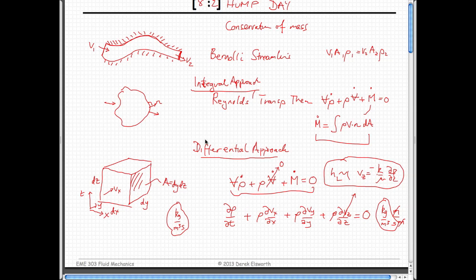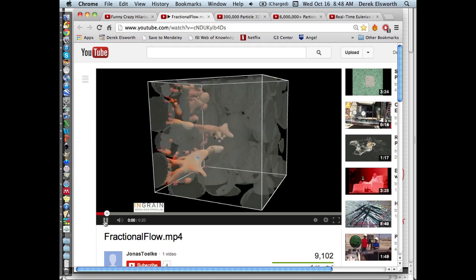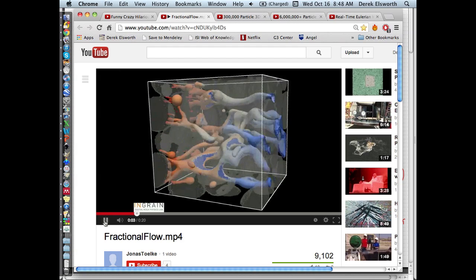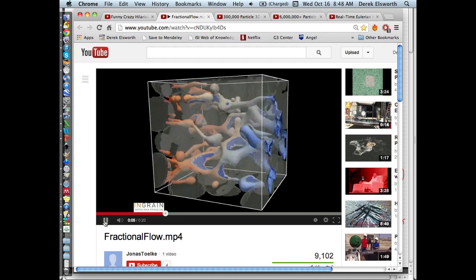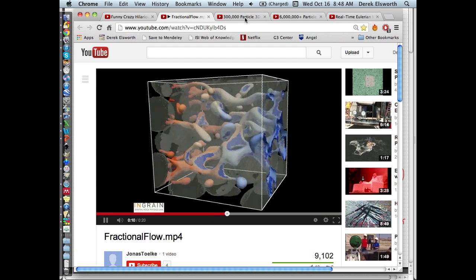And it's exactly the same as these expressions that we've used for rudimentary conservation of mass, a more sophisticated way of writing conservation of mass, and ultimately writing conservation of mass just for a little cube that happens to be dx, dy, dz in size and is exactly analogous to this expression. And so the bottom line of this, if I run these things again, is it allows you to divide systems up into a whole bunch of small cubes, and you look at masses into the side of the cubes, masses out of the side of the cubes, and to be able to figure out exactly what's going on.